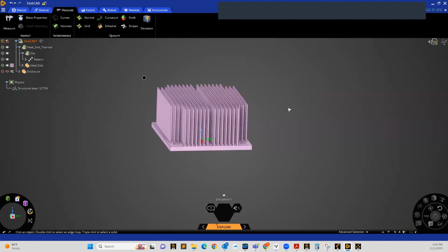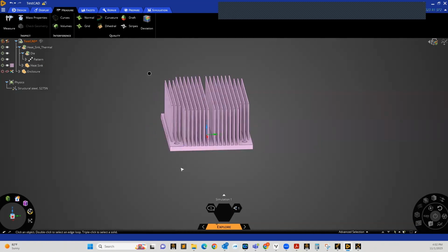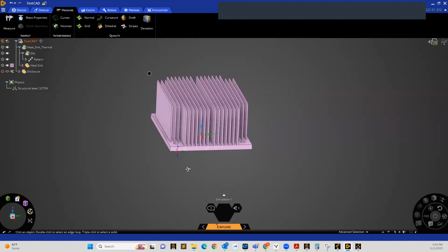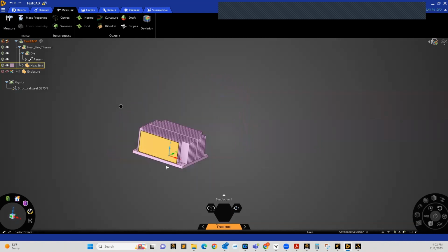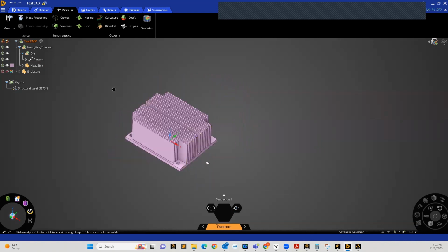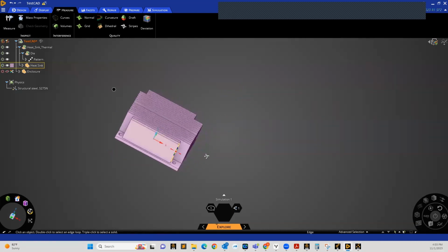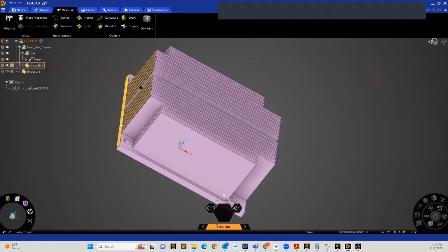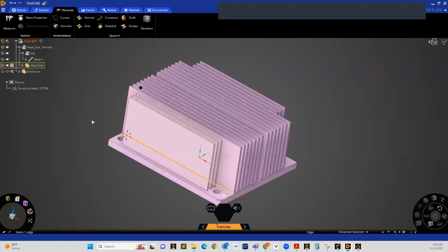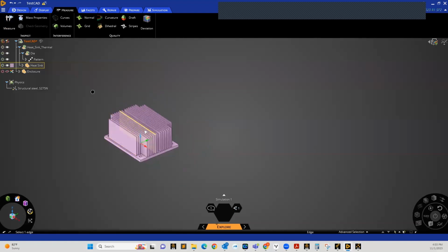So that's one simple, one-dimensional parameter that we can change, right? Another type of parameter, another thing that we can change: let's say we don't have a super obvious reference point. Let's say that we want to vary the length of this heat exchanger as well. In that example, we would need to set some kind of reference point, and the reference point can either be the other side of this heat exchanger here, like I used for the height of my fins, or it can be some arbitrary point in the center.